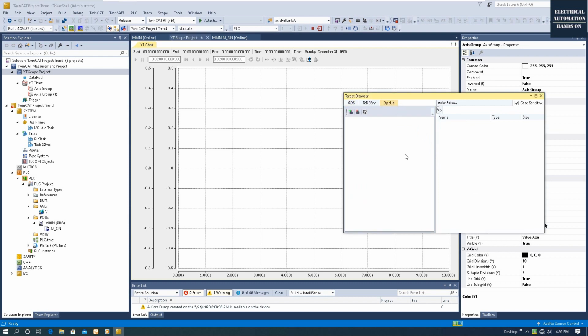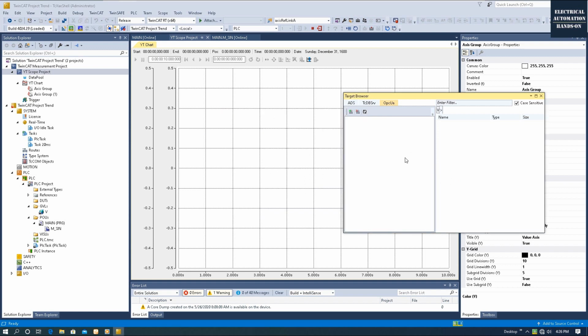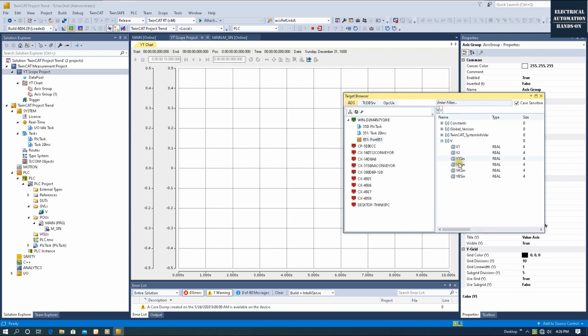That means even if you are not using a TwinCAT PLC, for example, you are using a Siemens PLC, Omron PLC, or Sysmac Studio, those PLCs basically all support OPC UA from the controller. So you can activate that PLC controller as an OPC UA server, and from here you can browse that OPC UA controller. It crosses brands and platforms. It's very convenient.